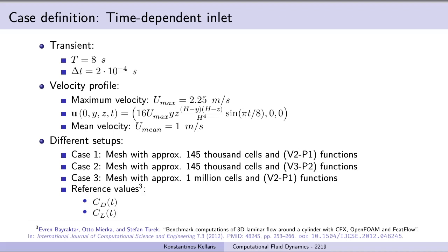The total simulation time is 8 seconds with a prescribed time step. The inlet profile is a function of time. 3 different cases were investigated. Cases 1 and 2 both use a coarse mesh, but in case 2 the order of the basis function is increased. Then case 3 uses a more refined mesh with a lower order of basis functions. Then the time evolution of the drag and lift coefficient will be validated using the data found in the literature.